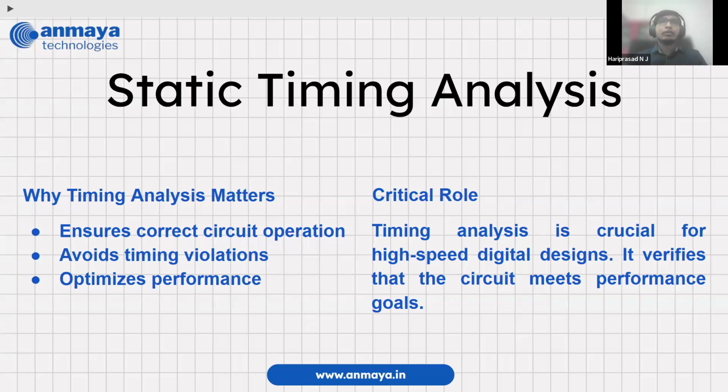Yeah. So basically, whenever I say a timing issue, we encounter some unknown state. In the data part, we will be encountering some kind of unknown data, mainly due to timing violation. We will see how that unknown state is created. We usually call it the metastability state.